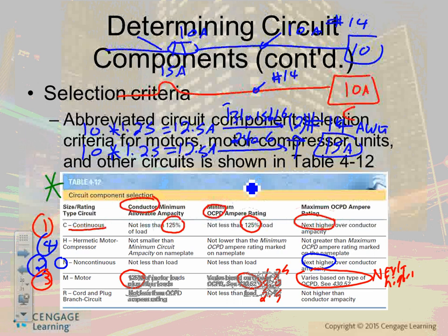It is a compressor that compresses the refrigerant. These are a special type of motor that is cooled while it's compressing the refrigerant. Because the motor is cooled by the refrigerant it's compressing, they allow it to work harder than other motors. It's the only difference between the two.